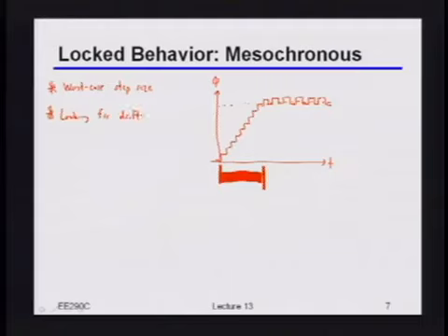So what do you want to do for that step size? You want to make it big, small, medium? Yeah, you want to make it small, right? Because basically the size of that step, the bigger it is, the faster I can track things, right? The less time it will take me to do that initial lock. And also, if I have some big noise event or some big errors, I'll just very quickly, quote unquote, correct for them. But of course, at the same time, if I have a really big step, then even when there's no noise whatsoever, I'll just be jumping around with a really big magnitude, right?